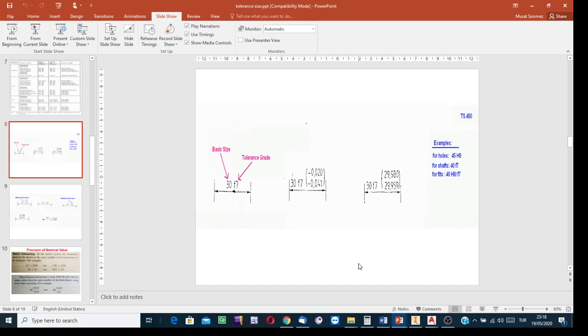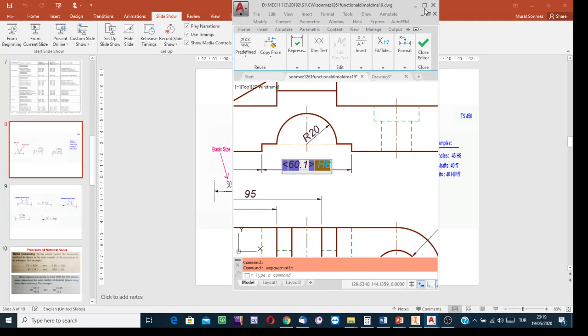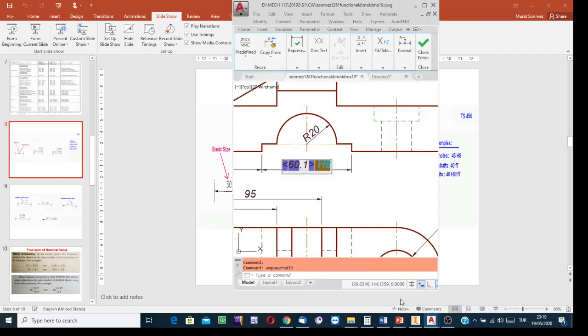In AutoCAD you can do it, but preferably show the limiting values, because a technician may make a mistake adding 30 and this one up. Show the limiting values, but in AutoCAD it is impossible to show the limiting values, you can only show the deviations. Well, here actually I made a wrong click probably, and since I am in the process, okay, continue.